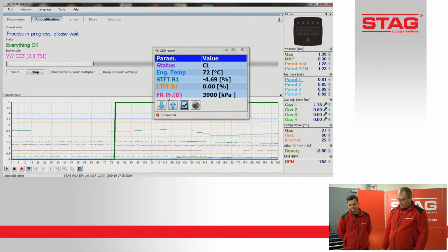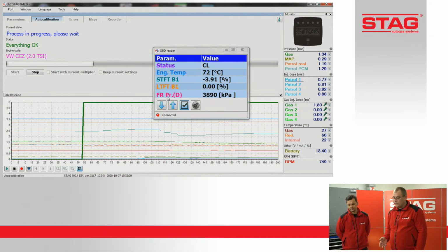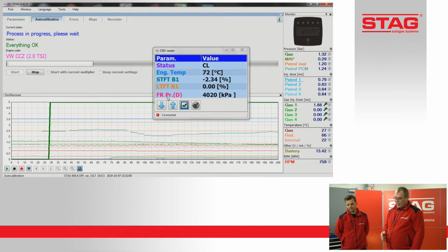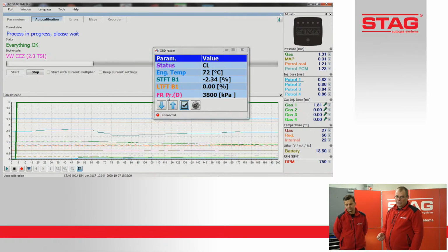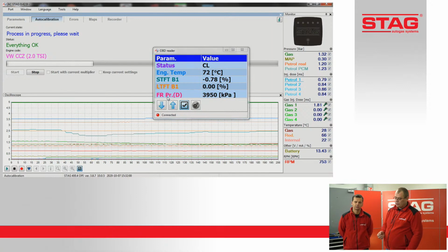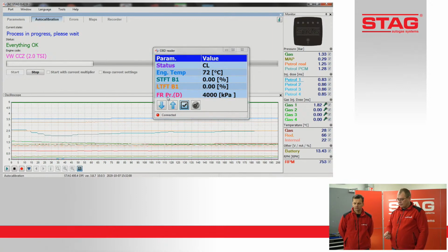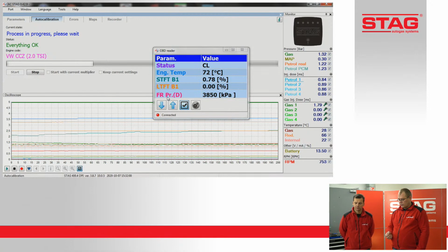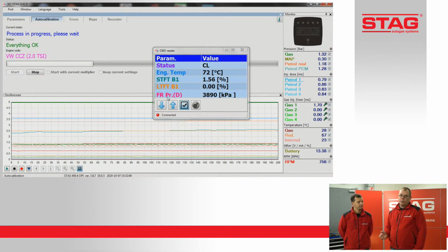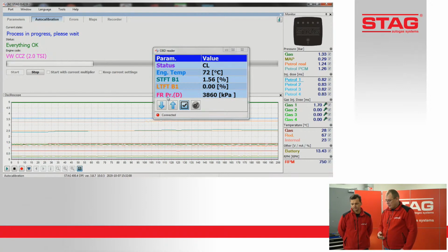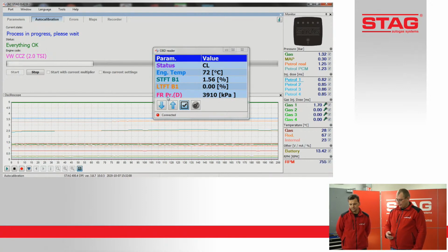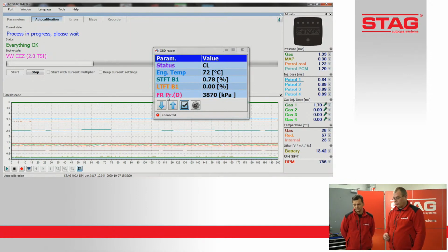And as we can see, gas injection time is very short, 1.8, 1.9 milliseconds, which means that these injectors barely even open, because 1.7, 1.8, like right now, is the border opening time for gas injectors. Everything below 1.7, the injector will open randomly, and it will not work properly. In that case, it means that something is wrong. But let's wait. Maybe it will pass the auto calibration.